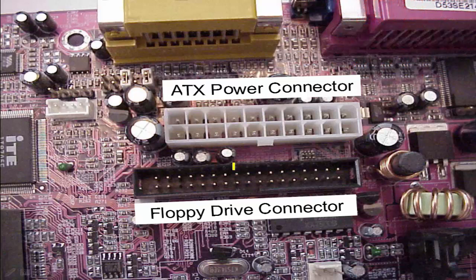Some of them may think that the motherboard is not working, so don't think like that. Just check your SMPS, the switch mode power supply, from which power is coming. If it is also working fine, then you check your processor whether it is connected properly or not. Similar kinds of primary measurements we can take before we give it to any technician.